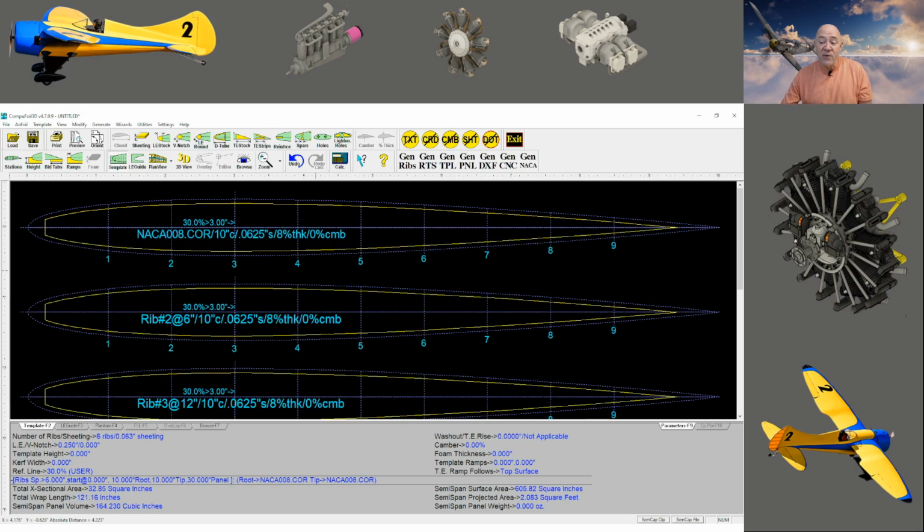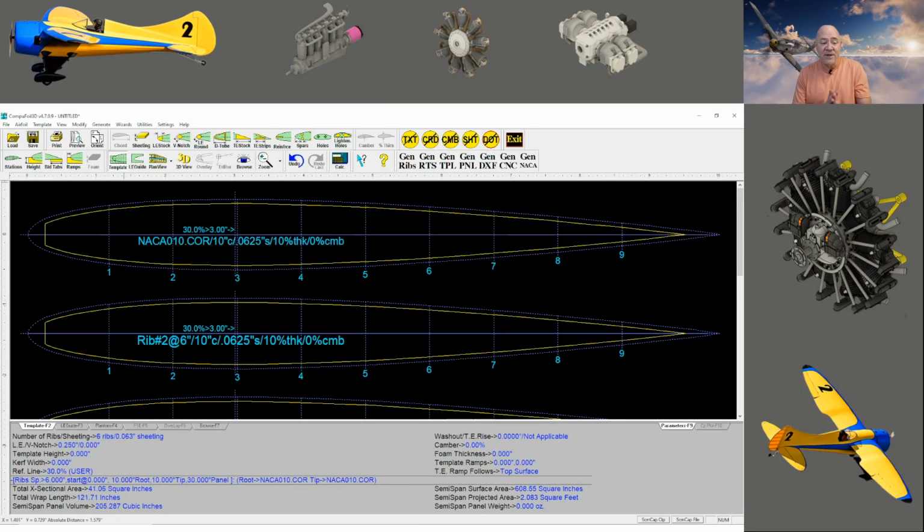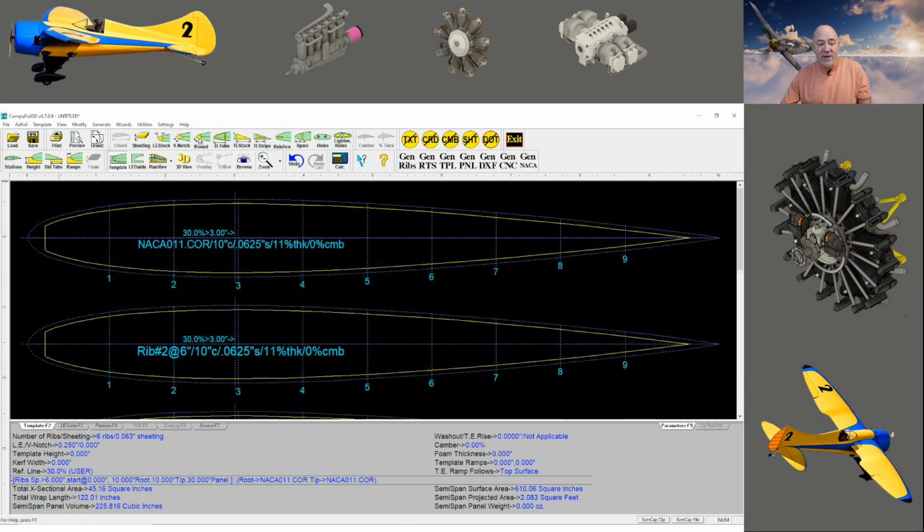This is one I use on both horizontal and vertical stabilizers. This one, which is the 10 or the 010, I've used as horizontal stabilizers on 80% of my airplanes. Okay, the MSL2 has this as the horizontal stabilizer, except I've rounded the front a lot more. It's not a very pointy tip on the stabilizer. And this right here actually was the airfoil I used on my C-130, but I gave it a 3.5 degree positive incidence. I'll show you later on how I do that on some of my other airplanes. But these are just basic, fully symmetrical airfoils.